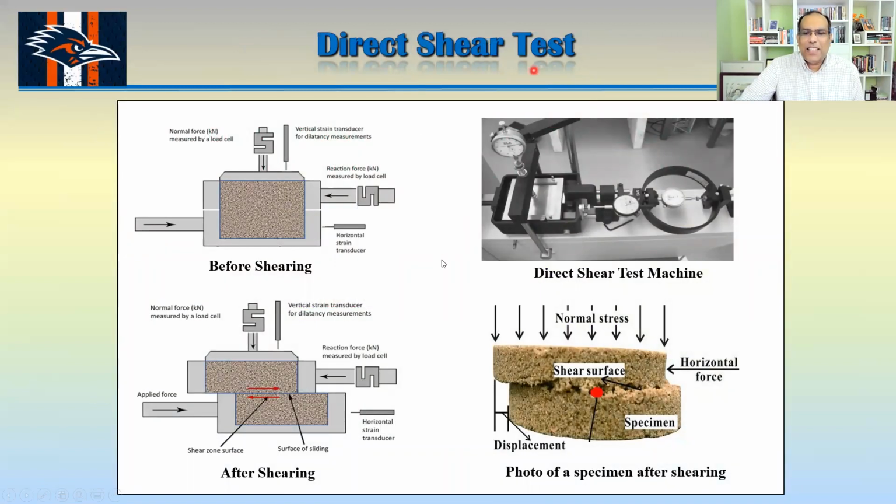That's the direct shear test instrument. You can see here the shear box, which I showed separately, and this part is what moves the shear box. If you look at the shear box, there are two parts, one on top of the other, and they don't have any lock.